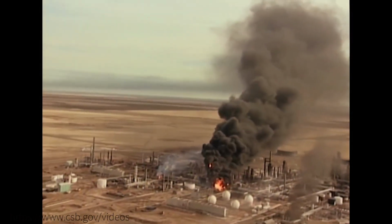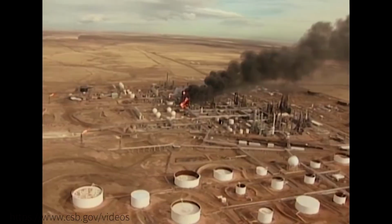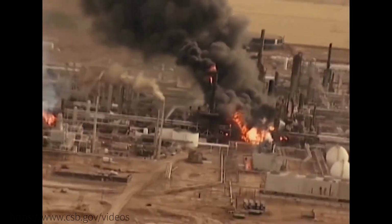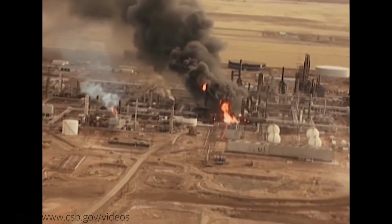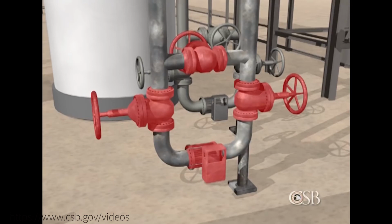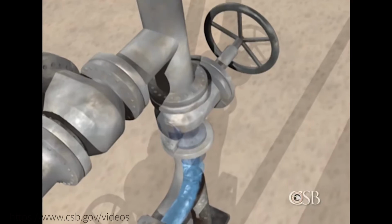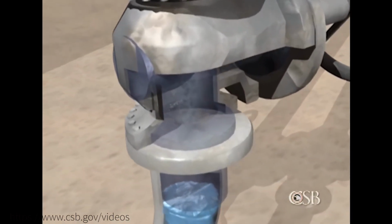The CSB found that lack of winterization procedures also contributed to a massive fire that took place in 2007 at the Valero refinery near Sunray in the Texas Panhandle. The fire occurred in a unit that used large amounts of high-pressure liquid propane. Years earlier, the unit had been reconfigured, creating a dead leg, or a section of piping without any flow of liquid. Dead legs are particularly vulnerable to the hazards of freezing, and the dead leg at Valero was blocked on one side by a leaky valve.